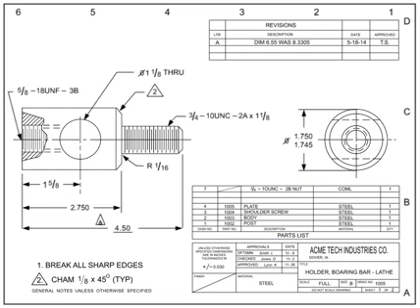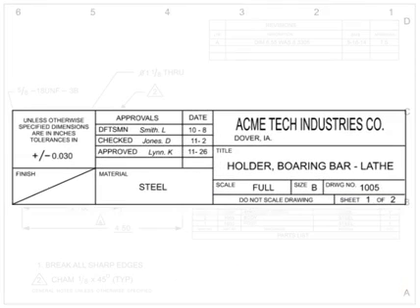The first place to look for information about a blueprint is on its title block. Most title blocks are located in the lower right-hand corner of the drawing. Although the title block information can vary by company, certain information is basic. The title block, at a minimum, contains a company's name and usually includes its logo and address. The drawing title block can also be called the noun or nomenclature. A short description of what the item depicted is, or the name of the part, is typically located in this block.